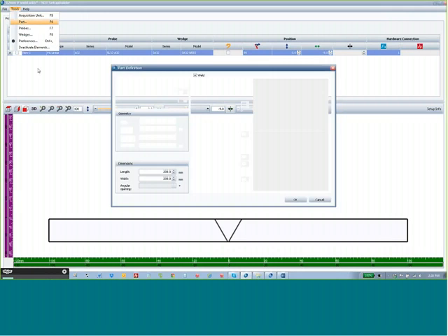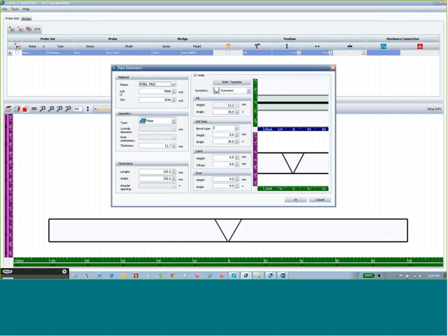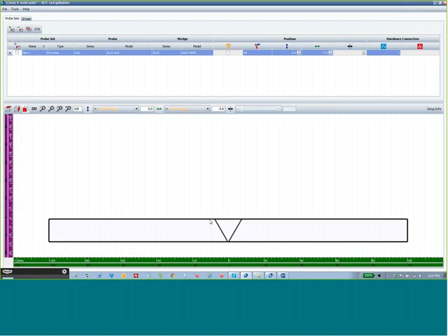We will define the part based on its material type and geometry. We will create the weld from a series of weld templates, populating the root, land, hot pass, and fill zones, and create our weld bevel.